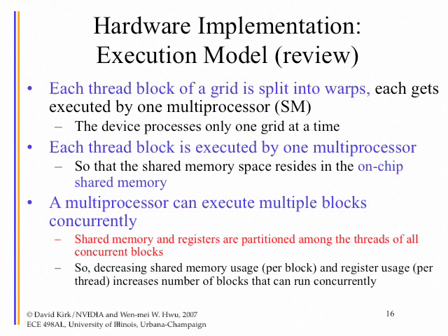Because underneath you, because you just used one more register, the hardware took out 1/3 of the threads running. Suddenly you lost performance. We're going to go back to this point, but this is the first taste of what we call the performance cliff on this piece of hardware. That cliff is something that you want to stay away from.